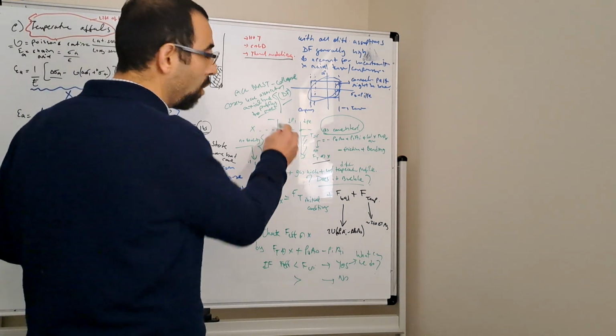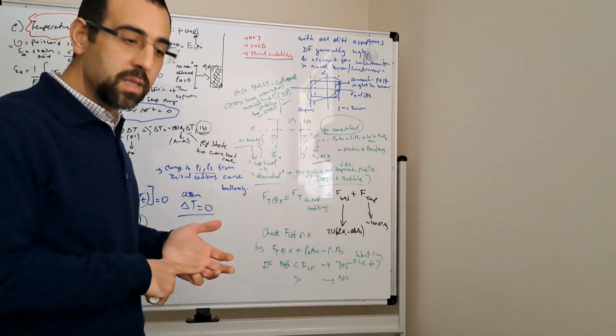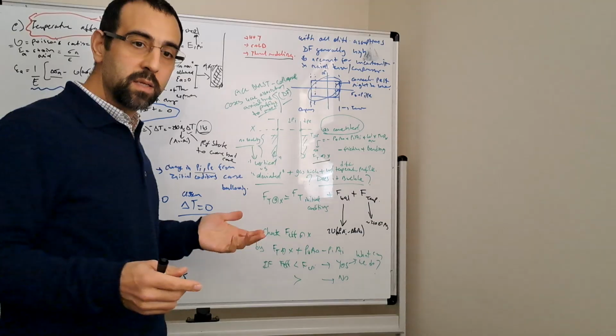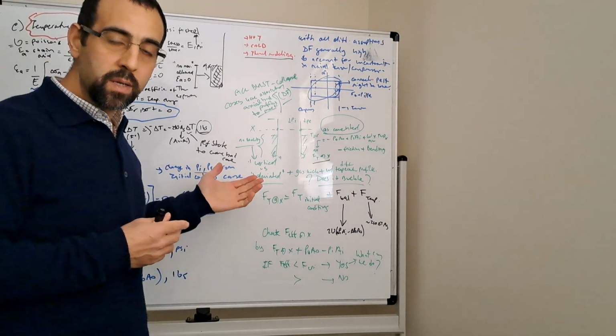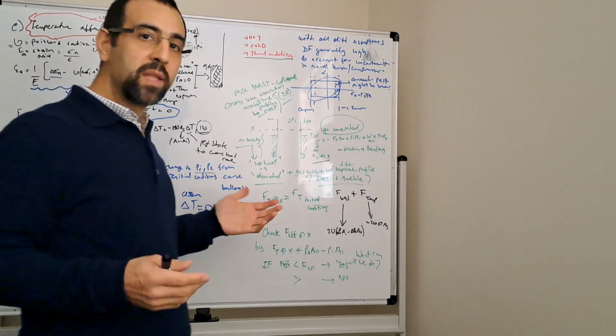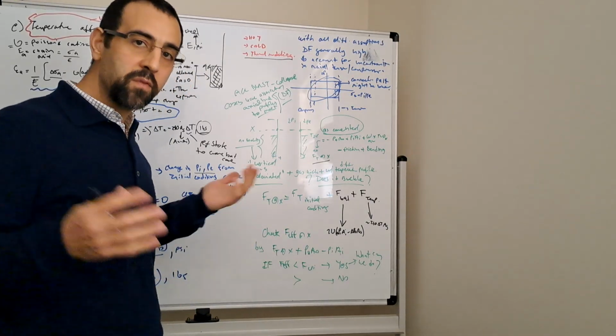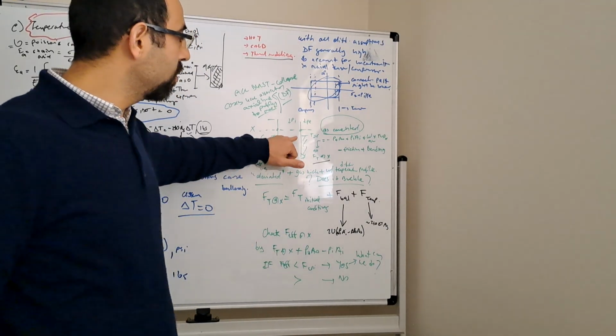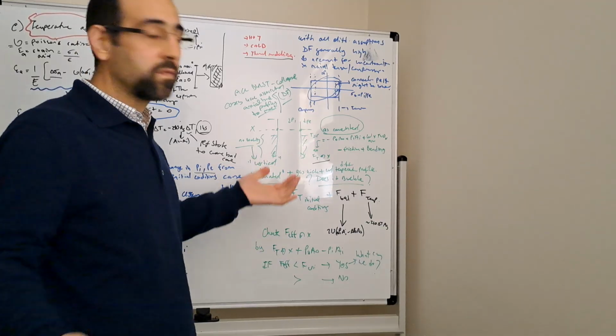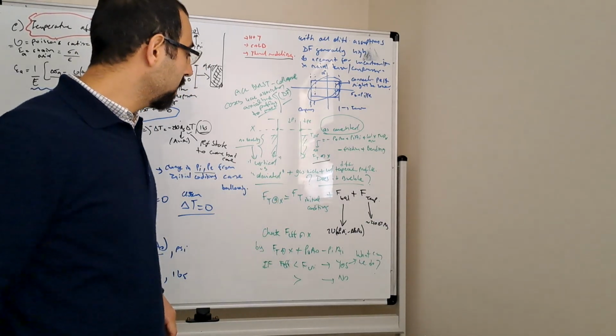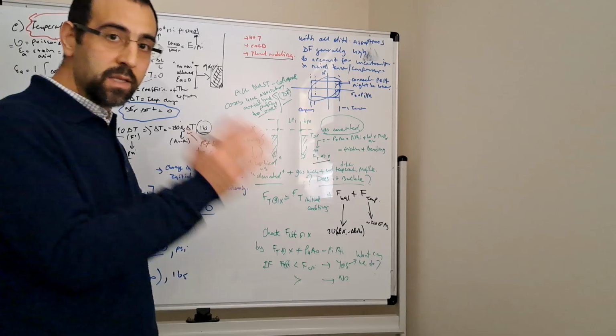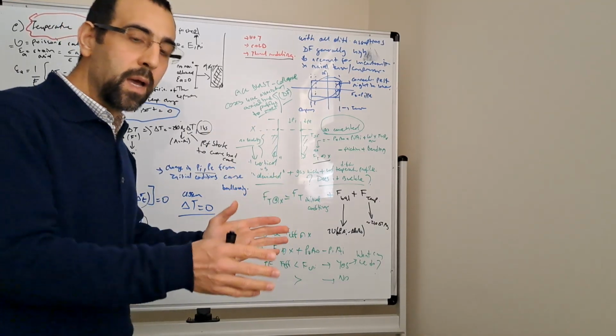So then you also accounted for any friction in the wellbore. It might be deviated. You remember the side force of weight times sine alpha times the friction factor, right? And then you accounted for bending. Let's say you accounted for shock load, and so you have the tension profile. That's locked into place, right?